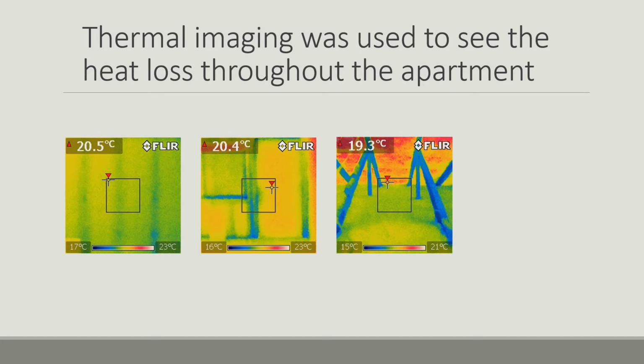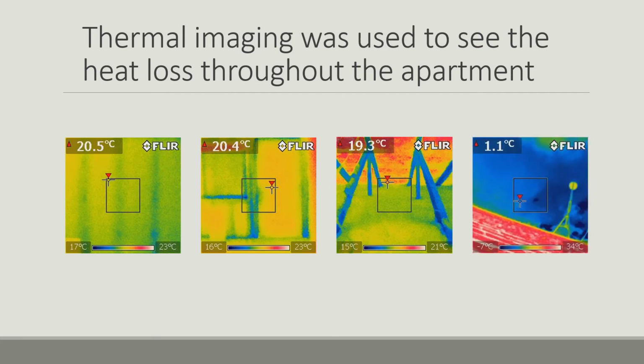After doing more research, we learned that insulation is best when it is not subjected to convection. Airflow causes the insulation to lose its effectiveness and act as more of a filter than an insulator. This made sense due to its composition and the amount of air circulating in the attic. Lastly, this is a picture of the roof and shows us some significant heat losses as we had previously calculated.